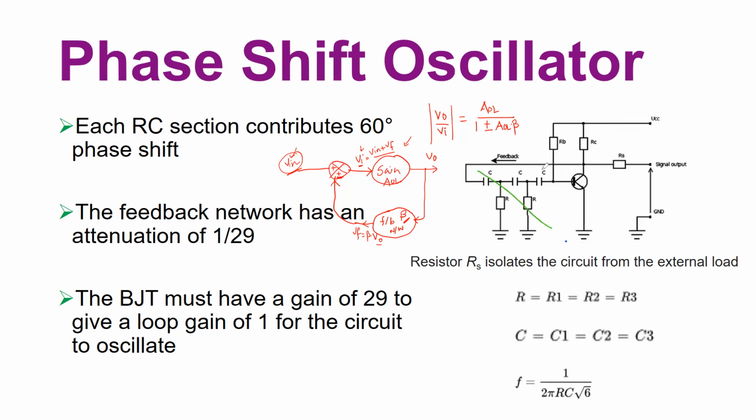So imagine you don't have this network for a moment, so at this node you apply an external small signal AC voltage source, and based on the transistor which is biased in common emitter mode, you will have an output, an amplified signal. So it would look like this. You have a small signal input, of course overriding the DC level set by the VBE here, and at this node you will have an amplified version.